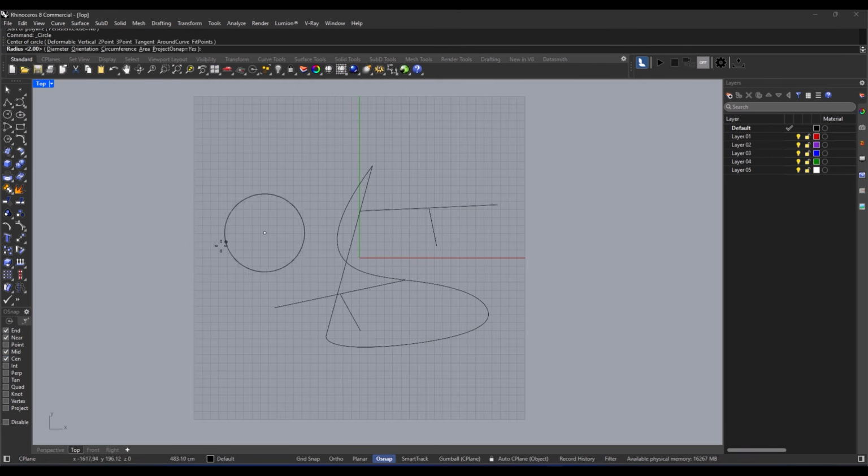This pinpoints the center of a circle or an ellipse. You could draw a circle on top of another circle or measure from the center. Pretty neat, huh? Quadrant. Think of this as one of the 4 main points on a circle or ellipse, like top, bottom, left, right. So you could draw a line straight toward the right half of the circle.